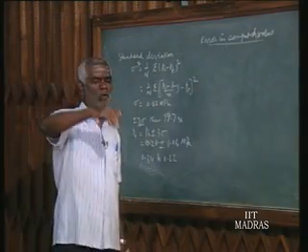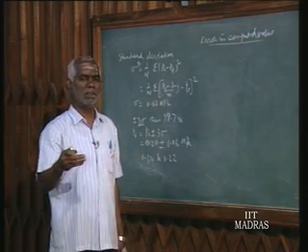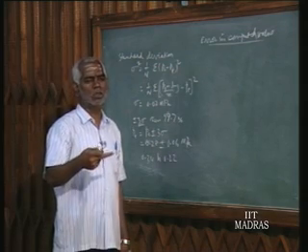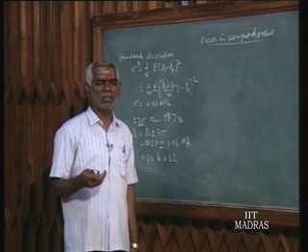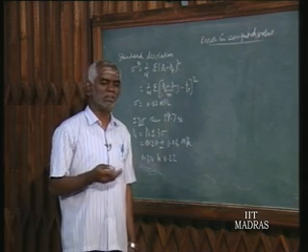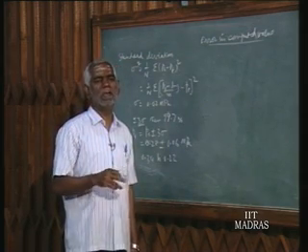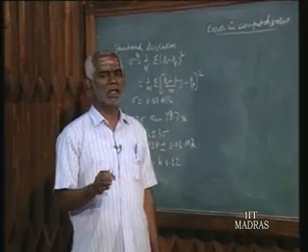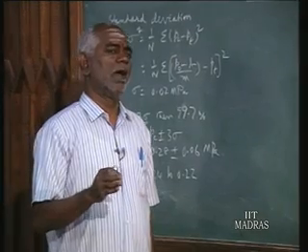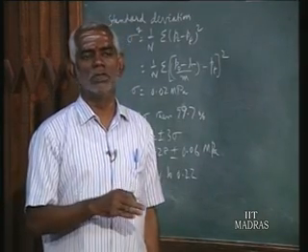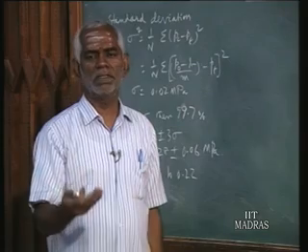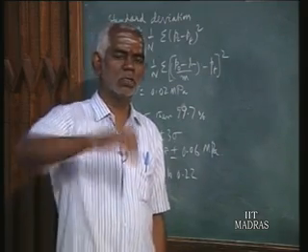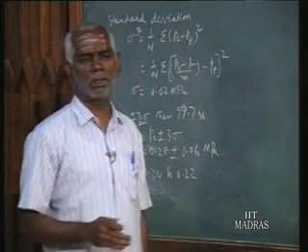Then you have to measure the flow rate of the fuel. Then you have to measure the power output in the shaft in terms of the torque developed in the shaft and the rotating speed. So 3-4 measurements you have to make in order to find the efficiency of an engine. From these 3-4 measurements we are going to compute a value. And we also know any measurement has its own error zone. Now, what is the error of the computed value obtained from different measurements having different inaccuracies? That is why we say how the error propagates into the computed value. That is error propagation.